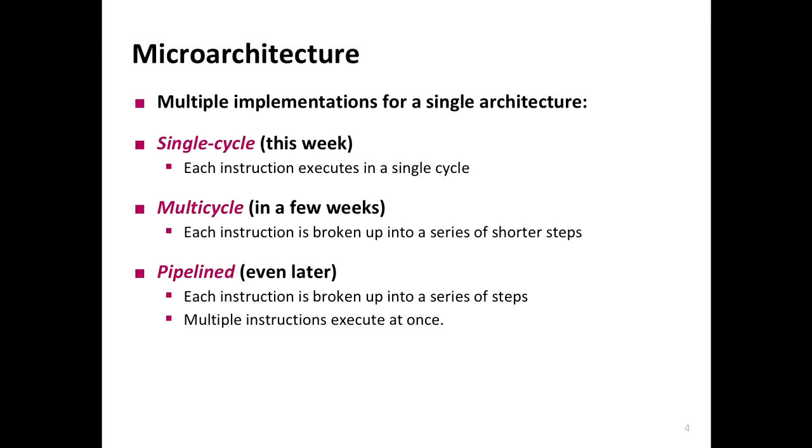So let's say you have some kind of a register read or write. And then after you have all the required values, what do you do? Execute it, right? Depending on the operation you have decoded, you need to perform the correct operation. And then you have to either store the result back into a register or into memory, or probably you will not do any store operation. You just go to the next instruction.